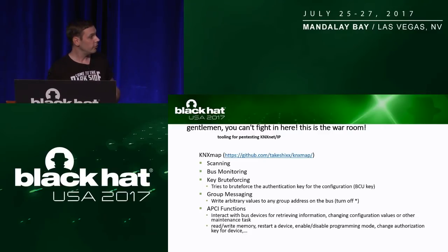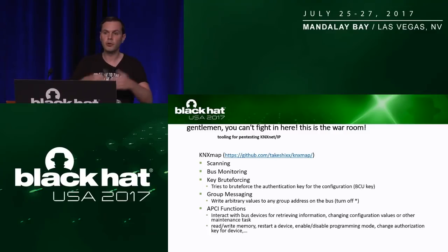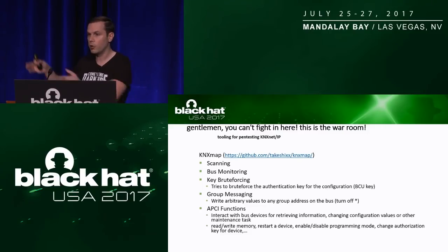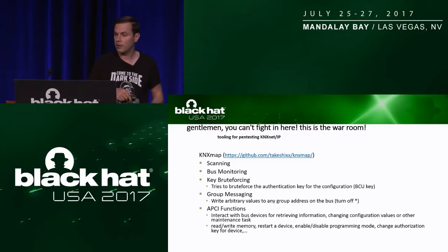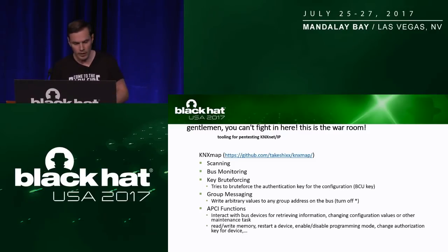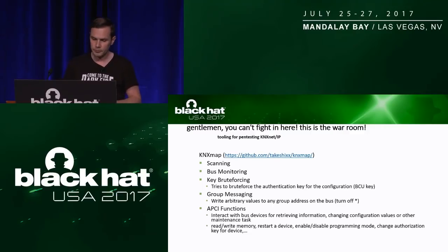Then there's group messages, so if you want to send the same command to a number of devices, for instance, switch every light in the building off, that's probably what you would use the group messaging function for. And if you want to talk to specific devices, APCI functions. Like restarting a device, enable, disable programming, that's pretty much it.